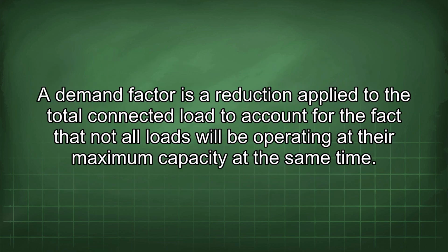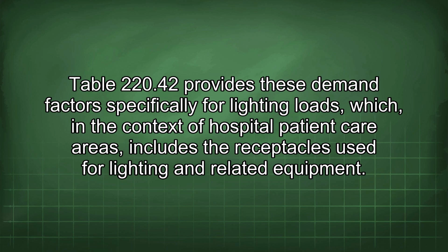A demand factor is a reduction applied to the total connected load to account for the fact that not all loads will be operating at their maximum capacity at the same time. Table 220.42 provides these demand factors specifically for lighting loads, which, in the context of hospital patient care areas, includes the receptacles used for lighting and related equipment.